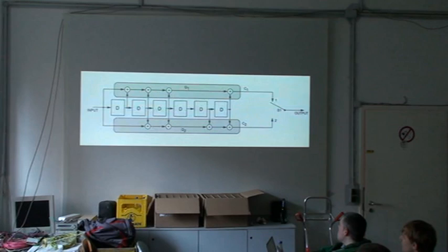And you have two of these that are very carefully selected, and you have a total output that's an interleaving, an alternation of these two polynomials. For every input symbol, you get 2 output symbols in this particular example. So this would be called a rate 1/2 coder. You could have a rate 1/3 coder where you have 3 polynomials and every input gives you 3 output symbols. GSM uses rate 1/2 coders all over the place, except for a few cases in GPRS.